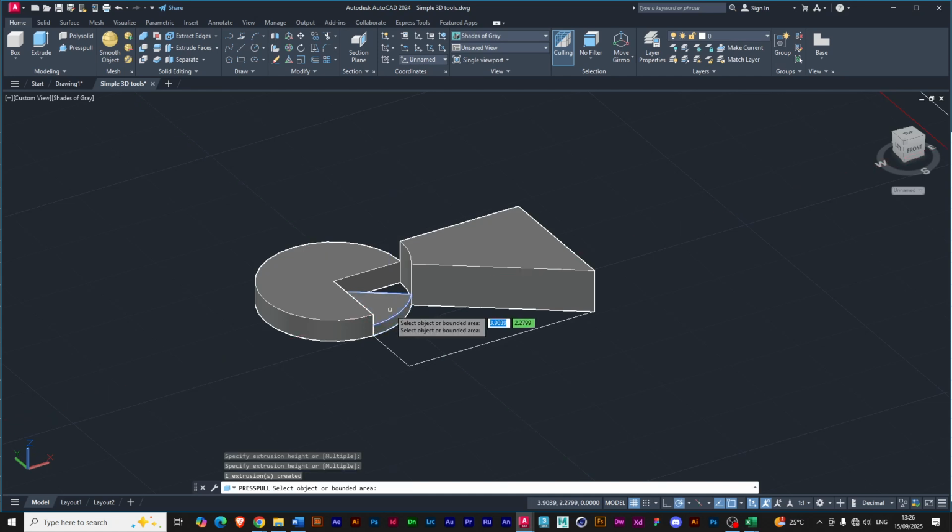Type mode. Click on, see the mode there. The shortcut is MO. So just click it. So see solid there. As you have clicked it, it's on solid. So just press enter. You can change from wireframe. You know it's on wireframe. That presents 2D wireframe. So when you have 2D wireframe written there, you changed any of the views.